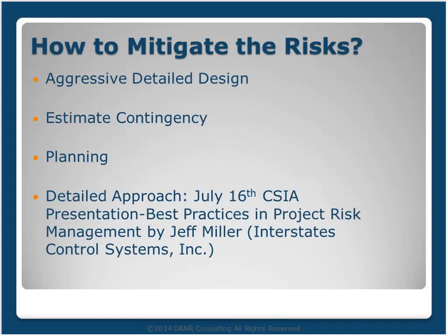So we're going to talk just a little bit more about risk mitigation. It's a complex topic, and I'm only covering it in fairly general terms. But first, when you encounter high-risk areas, spend that additional time and effort on the engineering design, as I just mentioned. One example is if the accuracy of an existing junction box termination drawing is a concern to you, then maybe you actually have a designer field verify point by point during the FEL. This will require more investment up front, but it lowers the risk in the project later on if the drawings are actually wrong.